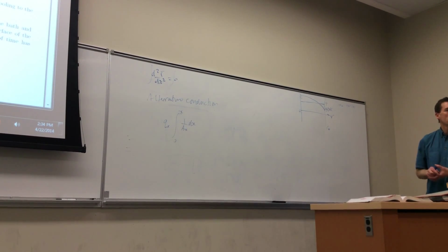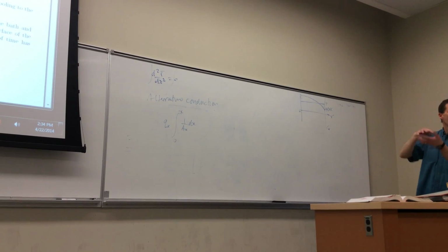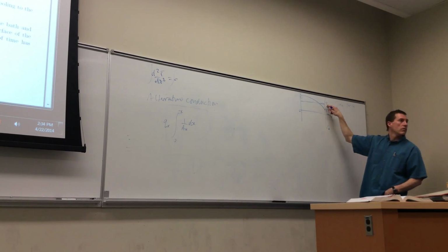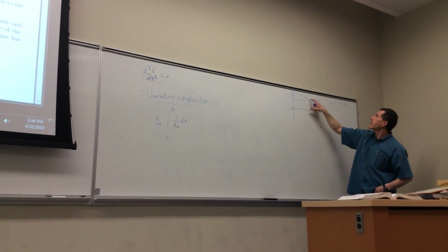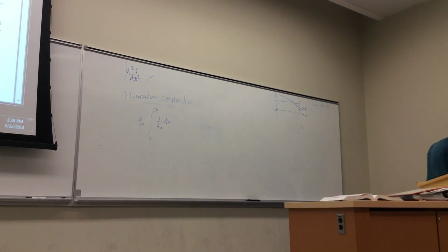Yeah. So you know that it's m Cp times Ti, or it's relative to T infinity, isn't it? m Cp (Ti minus T infinity). And then you can find the Q here. So then you can find the Q at the same energy content here at that time compared to this energy content. Okay, so was it not clear in the solution that that's what I was doing, or no?